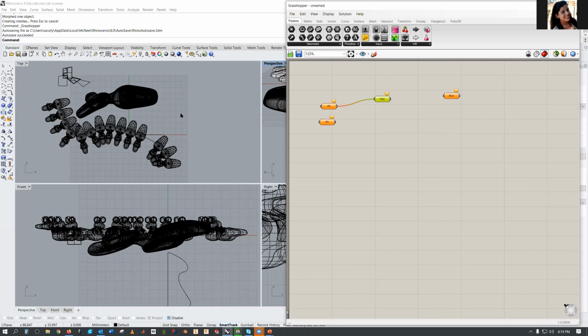What I've done with Rhino is basically I'll make things, and then I'll make copies, and then I'll make the next step, and then I'll make copies, and then I'll make the next step, and then I'll make copies. And that way I can always go back to that last step. Once I discovered that in the user parameters in Inventor and SolidWorks, that was a revelation.